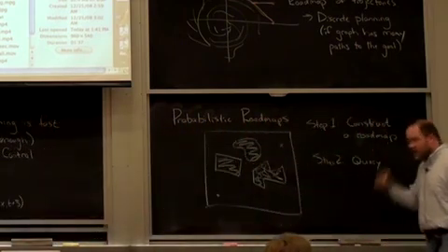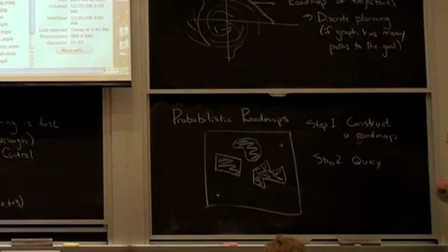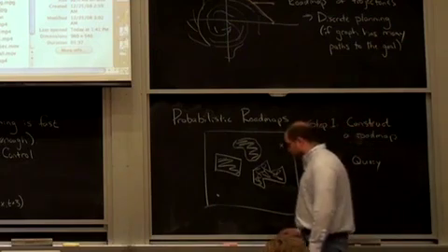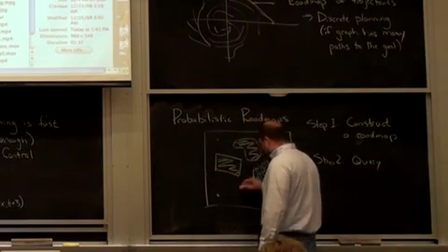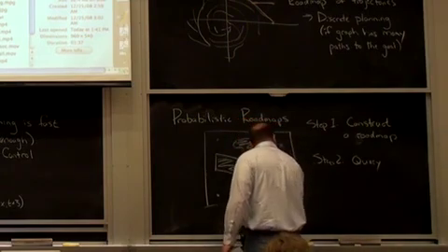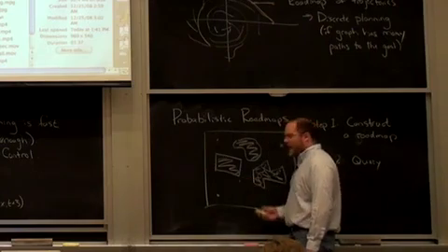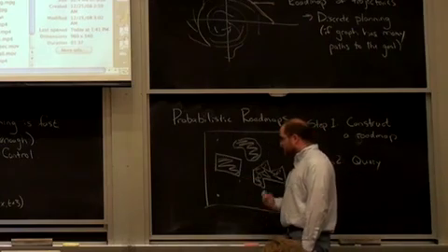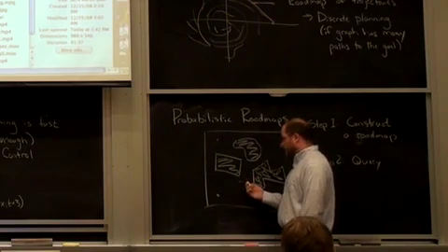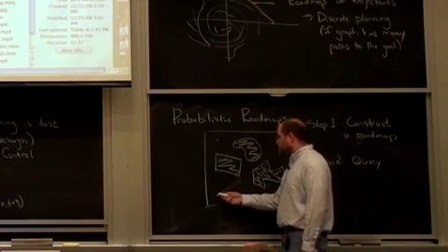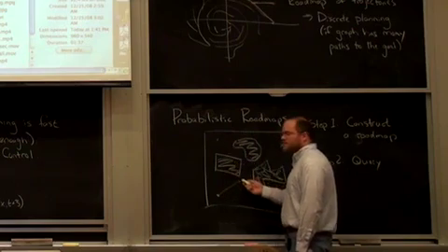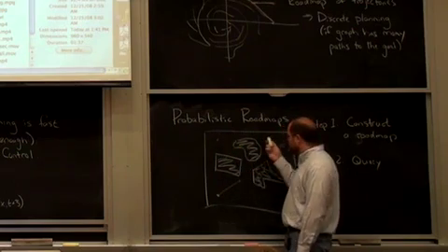So before I even start to solve the first problem, let's just drop in a lot of random samples throughout the space. Choose uniformly over the space. Every time I add a point in the configuration space world, I try to connect that new point to sort of the n closest points with simple strategies.